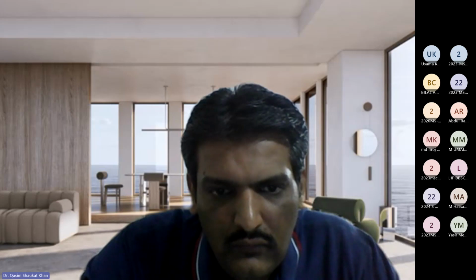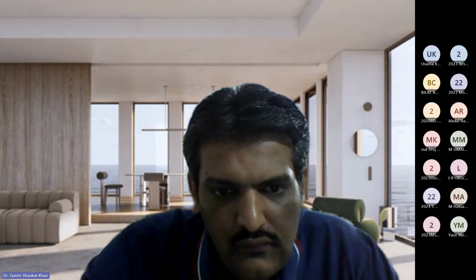Stress is equal to My over I, where this y is the distance from the neutral axis.